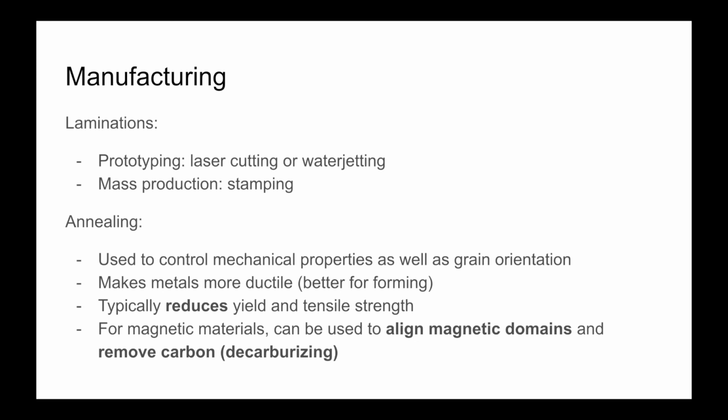For high volume production, stamping is always the way to go. It is much faster and cheaper after the tool is made. However, it does have the worst tolerance specs, meaning that proper tolerance analysis is required for carefully controlling the stacking process and controlling the air gap size.